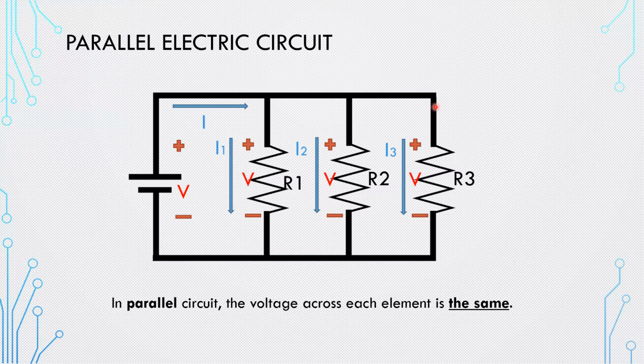As illustrated previously, to have a parallel connection, you have to look for resistors meeting at two points with no other element sharing them. If that happens, then I can call these two resistors in parallel. Similarly for these two, and overall I can say that all the resistors here are connected in parallel. Then this circuit is a pure parallel circuit.